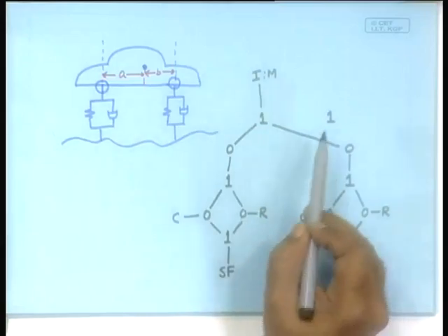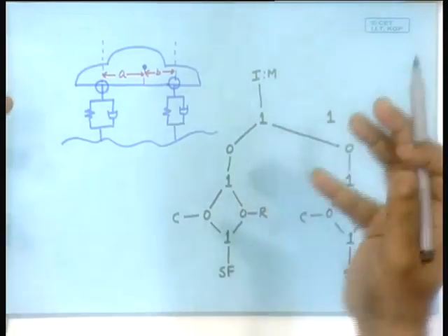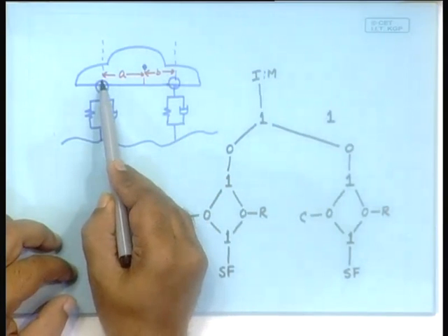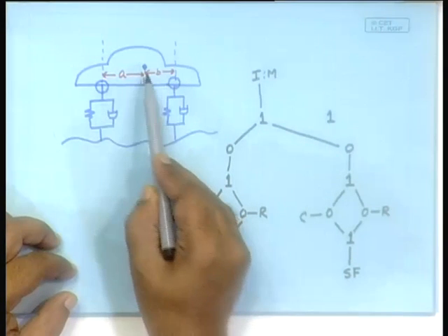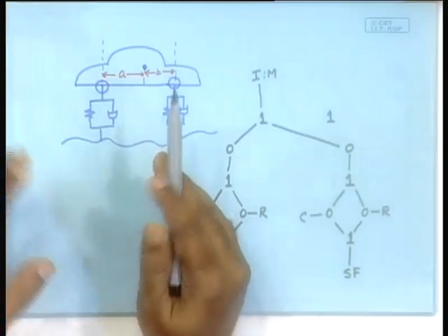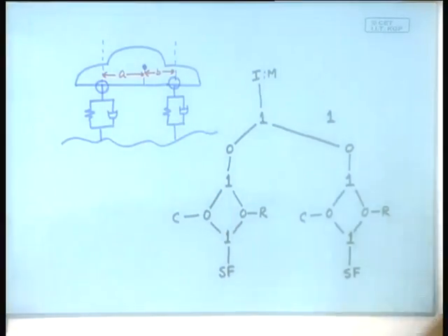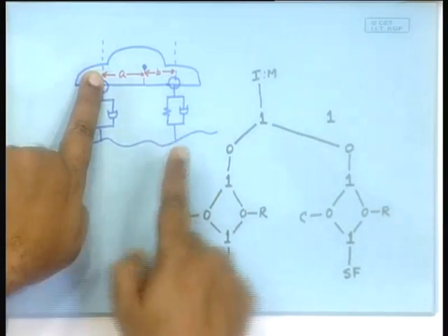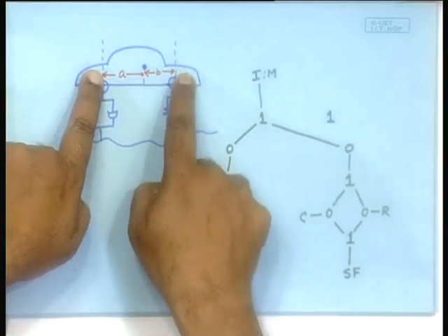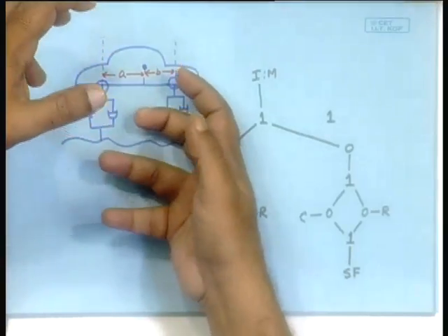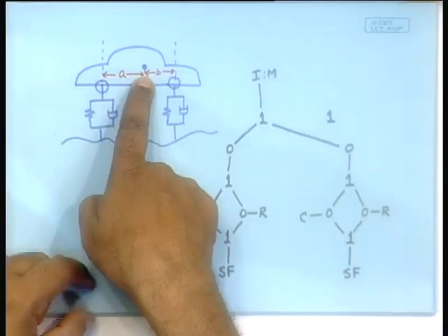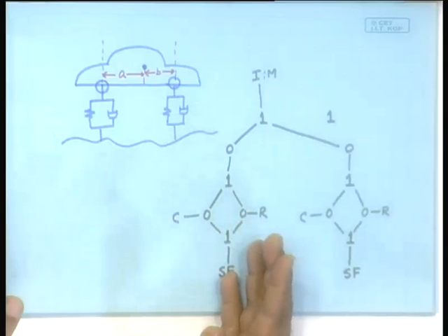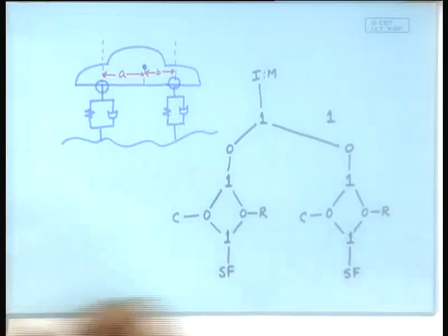Now, this is related to the rocking motion. The rocking motion, suppose you have applied a force here, you have applied another force here, what creates the rocking motion? No, not the difference. Yes, it is a moment. So, if there is a force applied, times A will be the moment, the force applied times B will be the moment, and so the torque felt by this CG will be, yes.